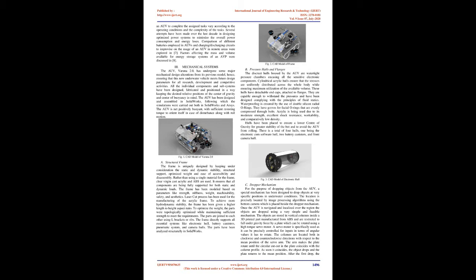B. Pressure hulls and flanges. The discrete hulls housed by the AUV are watertight pressure chambers encasing all the sensitive electronic components. Cylindrical acrylic hulls ensure that the stresses are uniformly distributed across the whole body while ensuring maximum utilization of the available volume. These hulls have detachable end caps, attached to flanges. They are capable enough to withstand the pressures and have been designed complying with the principles of fluid statics.